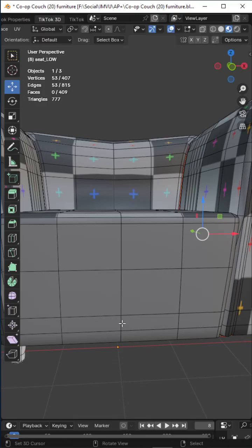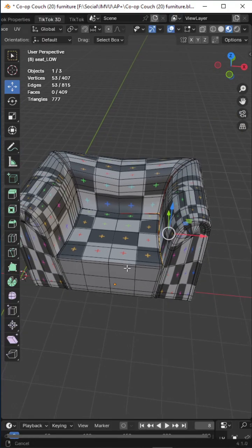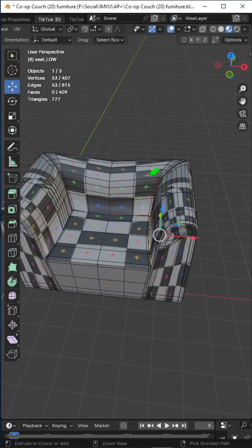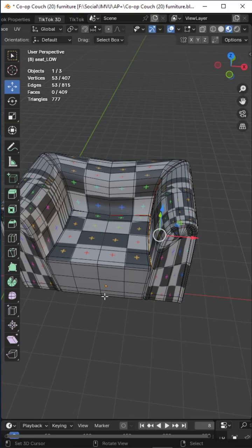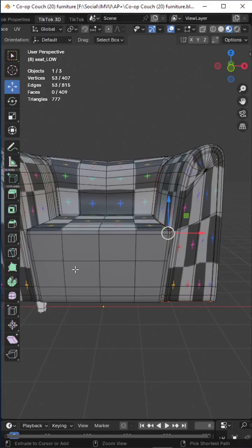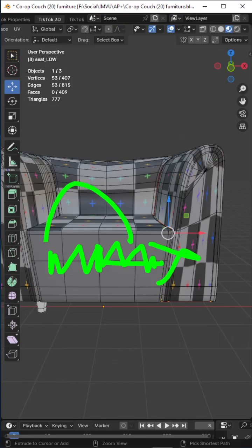So whilst we can use mirroring as an optimization, so essentially we just UV unwrap and texture one side of the mesh, it basically means that we are reducing the amount of texture space that's used, or the amount of textures that are used. They will be mirrored. So if we want something that's unique, let's say there's text written across the front here, only half of this is going to be used because it'll be mirrored and inverted as a result.